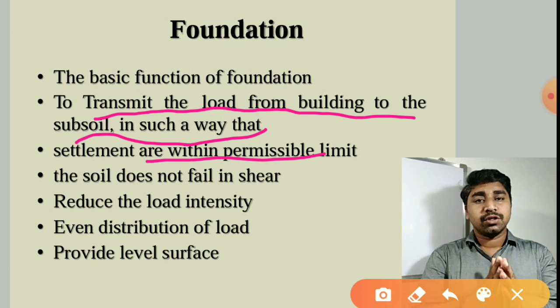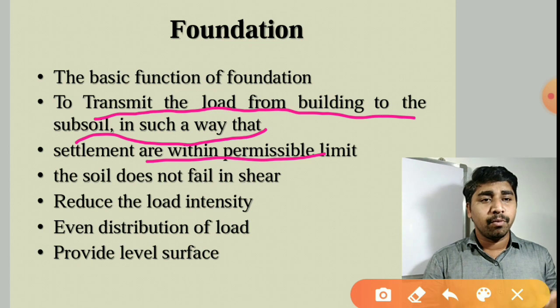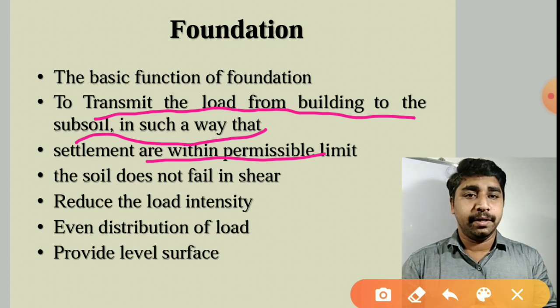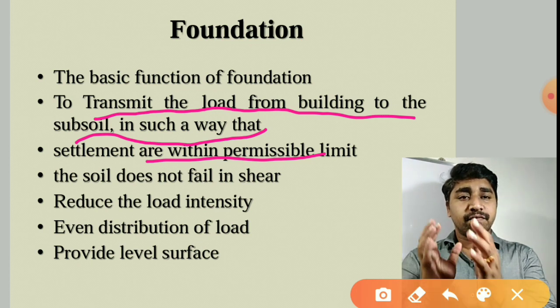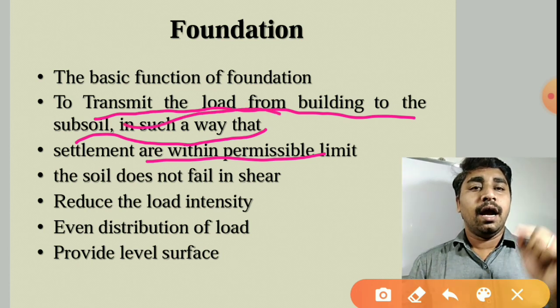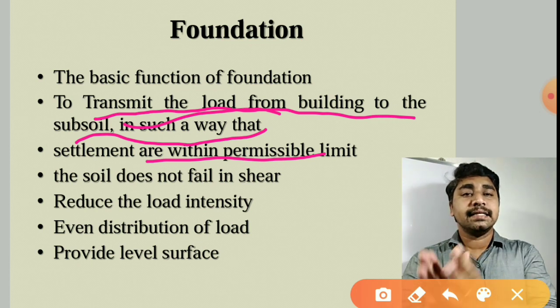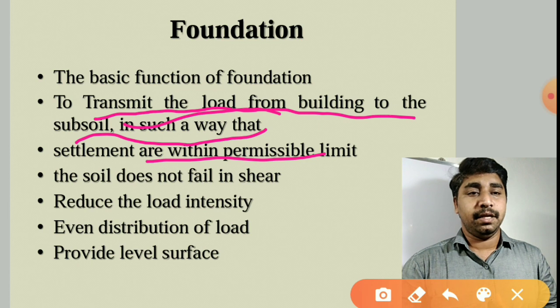So what should happen here? The settlement should be within the permissible limit. It should not be more. So the basic function of the foundation is to transmit the load from the building to the subsoil in such a way that the settlements are within the permissible limit.